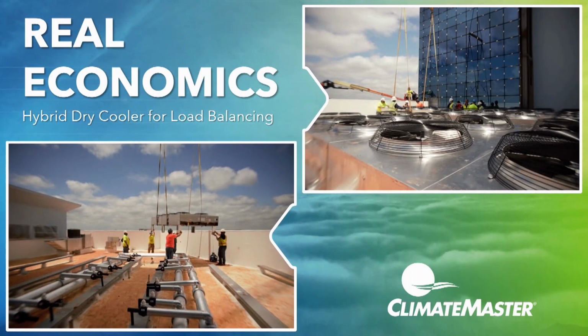In this case, there was a dry cooler array used to balance the load because that building rejects far more energy than it pulls back out of the ground. So this balances the load. So there were these Liebert dry coolers. I think there were 6 or 7 of them up there, and I can say we've been watching the temperatures in this building every year, and I look about every year this time, April. We're coming out of the winter, getting ready to go into the summer.